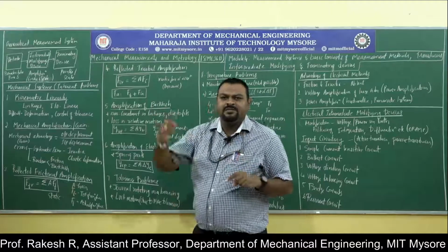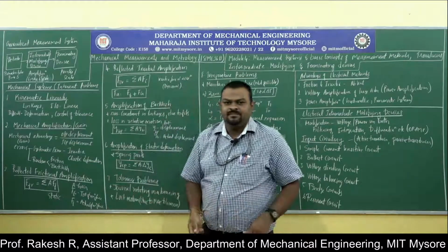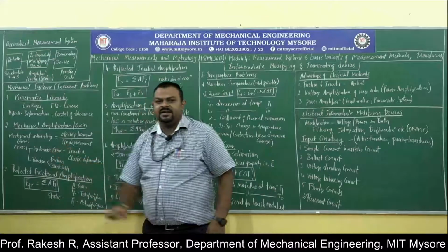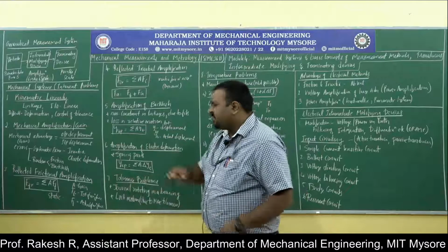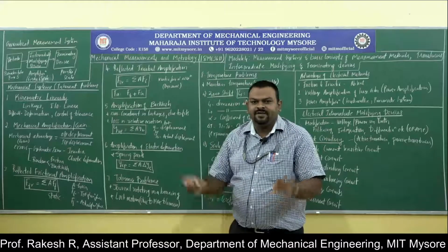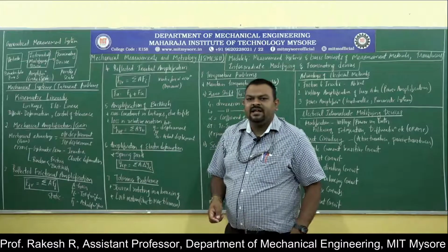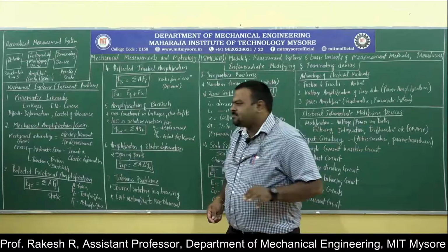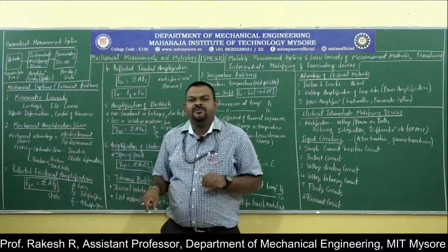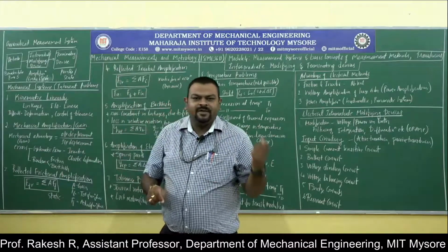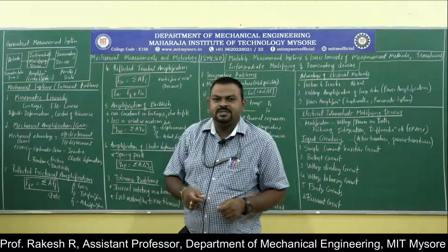At the next stage it will show some reading. Even though it will show some reading, that's why calibration is required. So these two errors will be there as linkages in a mechanical system. Whenever there is a mechanical system, you cannot eliminate friction and backlash. That will be there. So this is about gain or mechanical amplification. You need to explain how these errors will be affecting the transformation of the detection from the primary to telemetry or final stage, terminating devices.